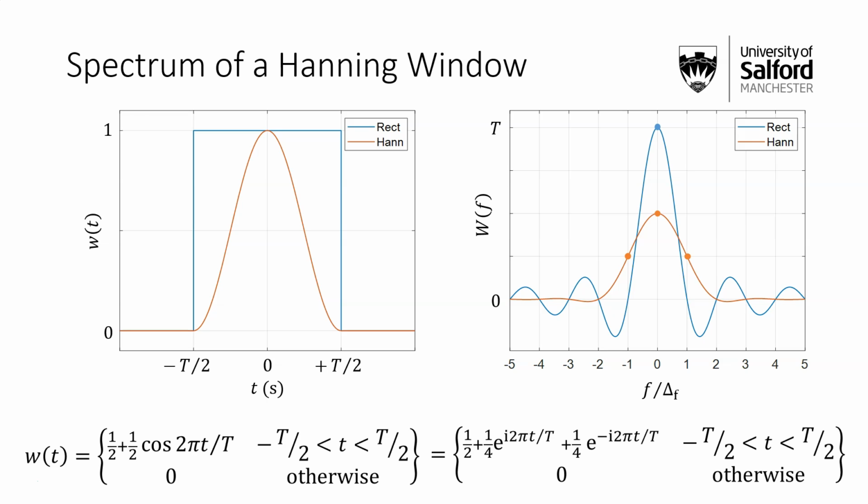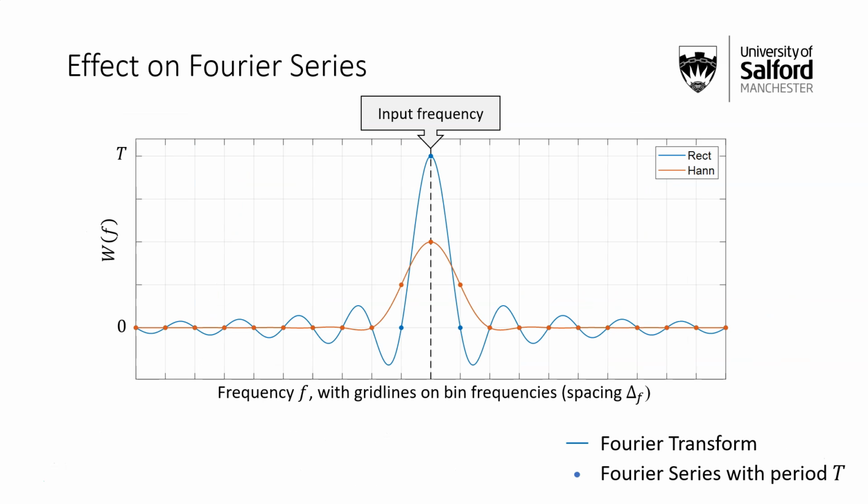But we can see that away from the peak it's reduced a lot faster. And if you want to use a Fourier series, so a Hanning window with a Fourier series, you'd see very little benefit. In fact, it would make it worse, because what it's done is spoilt the nice orthogonality property of the frequencies. We get some smudging, so actually we've got a wider main lobe.